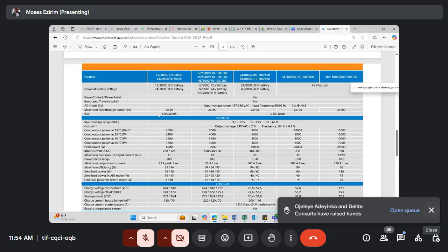Compared to where I bought the same, it was a 3.5 kVA, 48 volt, and I installed it. They said that one too was hybrid, and I installed an external charge controller, and that one was performing well. While the other 10 kVA wasn't actually performing well. The good thing was that the client doesn't stay in that place. It's actually his farm. So I don't know if it was really an inbuilt MPPT or a PWM or so.